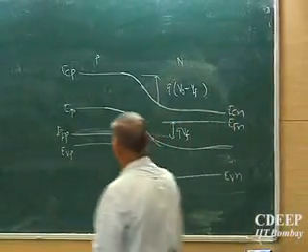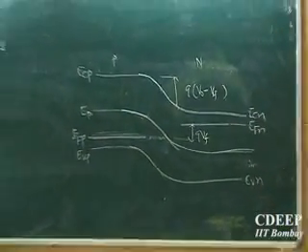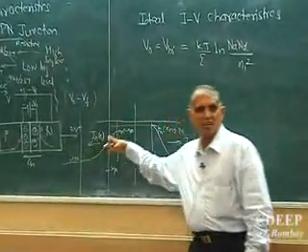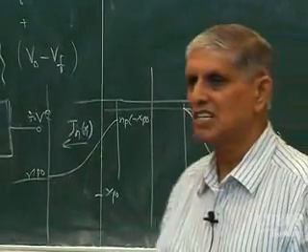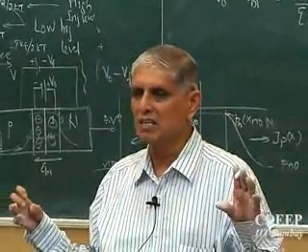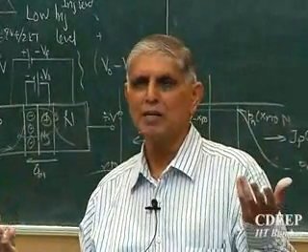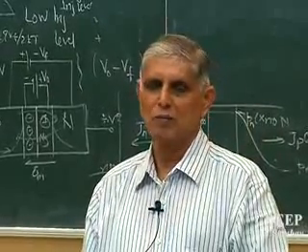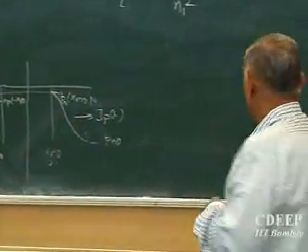I assume all this, I say everything is constant here, I don't worry, I only say they will diffuse, recombine, and since there are excess carriers, which equation will they follow in steady state? The continuity equation. But in steady state, the time dependent term is 0. Then I have a space dependent term, so I can always calculate dp/dx or pn(x). This is the technique which I use.